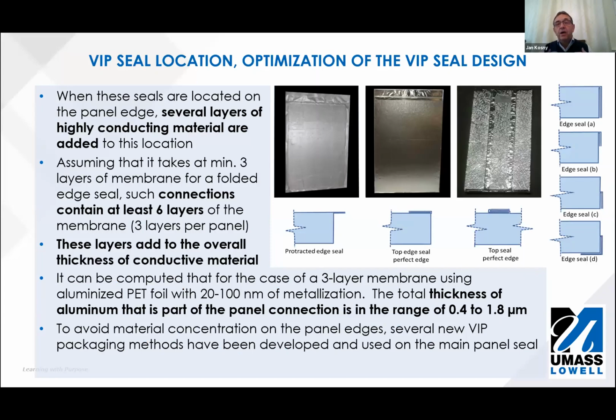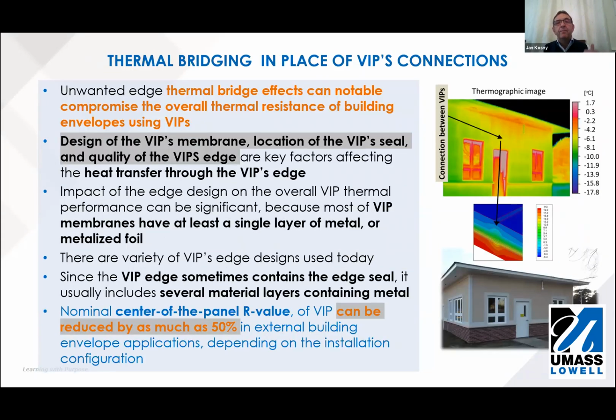Vacuum seal is something which is very important. Typically, because the technologies come historically from the food industry and pharmaceutical industry, those seals have been placed on the edges. As I said before, we try to minimize the amount of conducting material on the edges. Those seals are either folded in different ways out of the edge or placed completely differently. That's very critical for the design of vacuum panels for building applications, to minimize the amount of conductive materials on the edges.